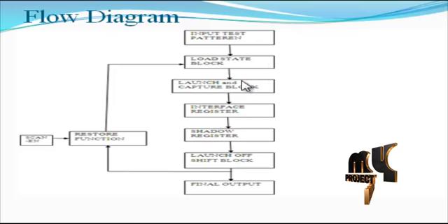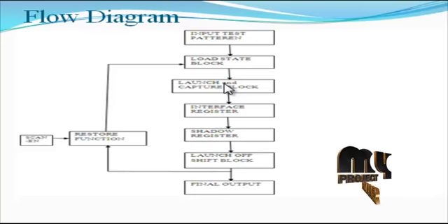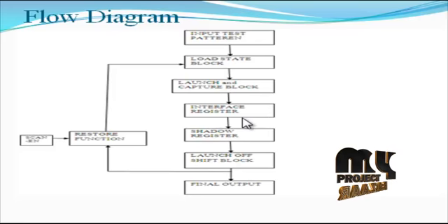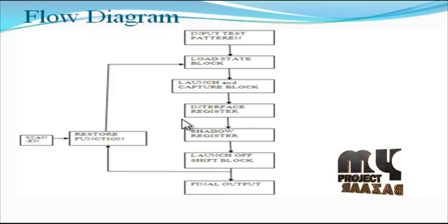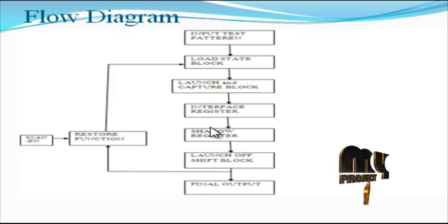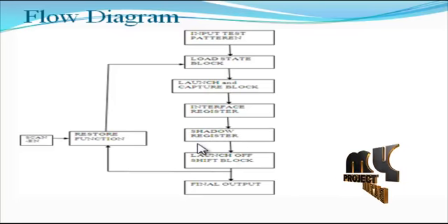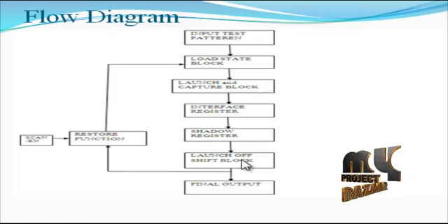The LOC block is processed by our testing architecture. Thus, the architecture passes to the interface register. The interface register is a clockless register element. A latching process is applied. Thus, the input is just stored in the interface register and passed to the shadow register. The shadow register finally holds the final test pattern results. The final test pattern results are stored in the shadow register and used to apply the launch off shift operation.